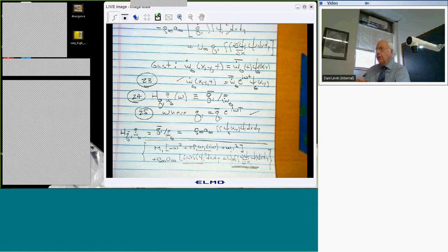So if you plot gust response versus Mach number versus velocity, as you approach the flutter or the divergence condition, the response will get bigger and bigger and bigger. And so you could do a gust analysis and predict flutter as well, although people normally don't do it that way. We'll tell you how they normally do it. But it's buried in the gust response analysis if you pay attention.